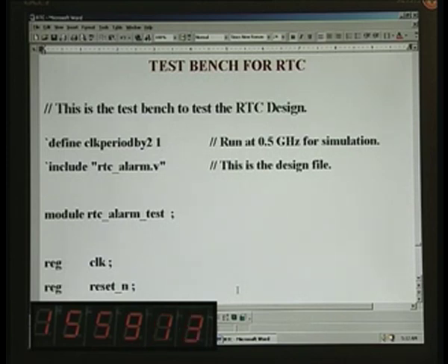See, for example, you want to push a button, what do you expect out of it? If I push once, you should increment only once, not 100 times. Erratically it will behave. If you do not debounce, it will give multiple pulses, because you are counting the pulses applied, it will be erratic. You expect just one increment, 1 must go to 2, but you will be annoyed to see 1 going to 8, 10 like that. So, that is the purpose of debouncing.